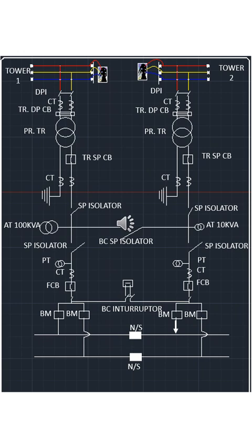And another protection is the overcurrent relay. If the number of trains running is beyond the current capability of the traction substation, or the traction transformer is overloaded, then the relay will trip the circuit breaker.